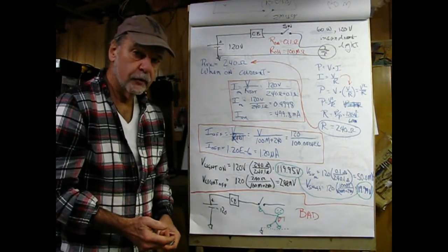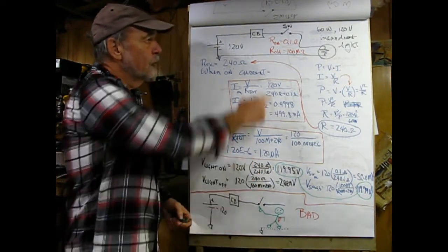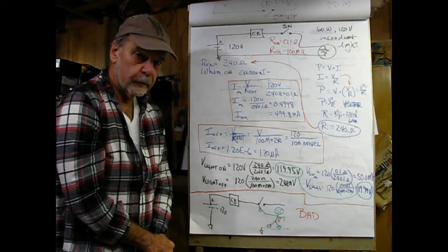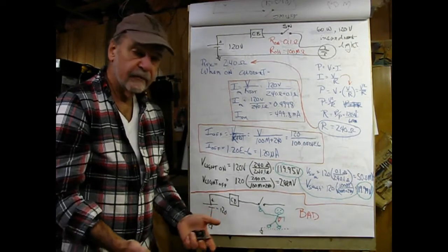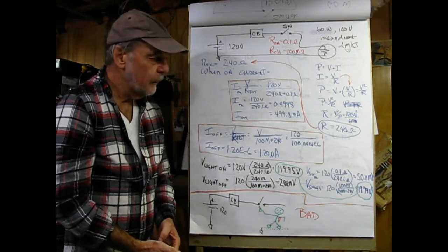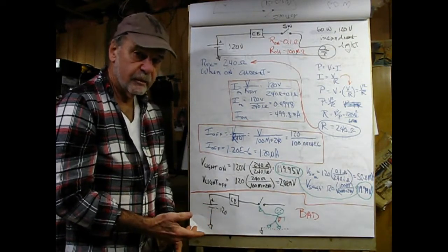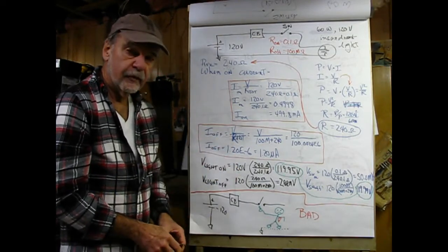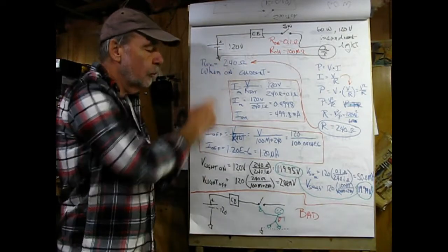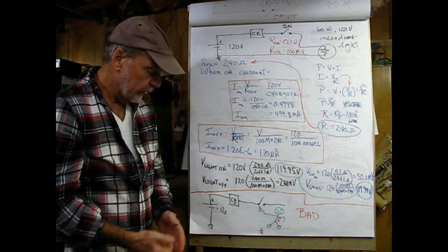So the point of this is, if you turn the light off, it does not mean that the circuit is de-energized. What you have to do is get down and open the circuit breaker. That means probably some clocks in the bedroom are going to have to be reset, and so on and so forth. But you don't take chances by playing with live wires, especially in the voltage range that can, well, how should I say, kill you?